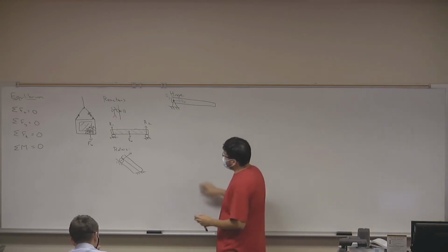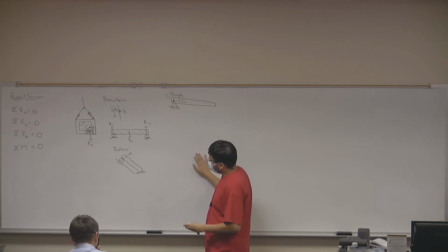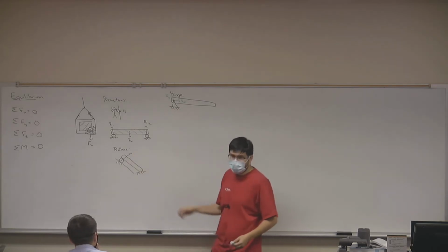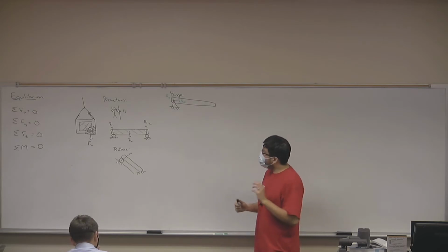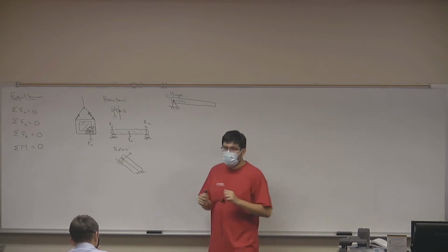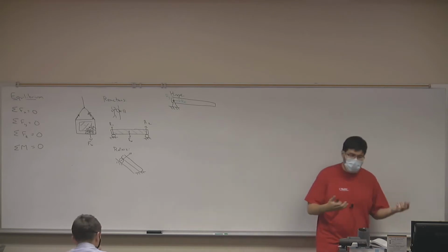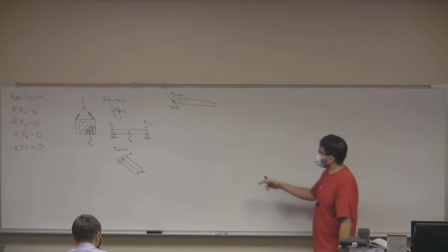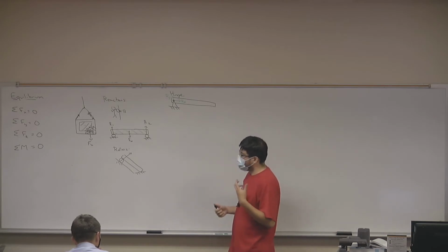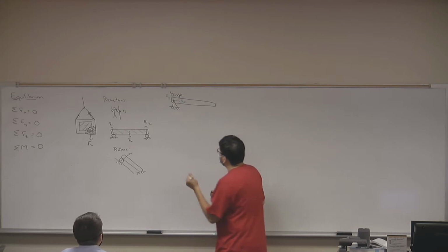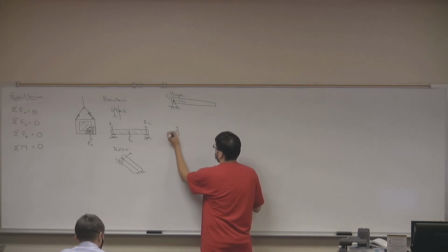Now, we've looked at two different types of supports. And these supports are preventing linear displacement. What other reaction do you think we need to account for? We're looking at linear displacement, so okay, our supports can prevent this linear displacement, but is there any other type of reaction that we need to account for? Moment, right? So we're going to define a fixed support.